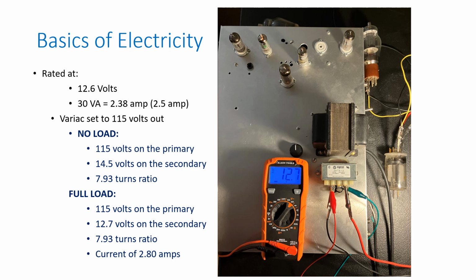So you might be asking yourself, well, now wait a minute. Why doesn't the voltage in my house vary when the air conditioner starts or the clothes dryer is running? Well, it does a little. It's going to drop a little. Here at the house, if I turn everything off in the house, I get 123.4 volts, about that. If I turn on the clothes dryer, the air conditioner, the oven, and the electric range and turn everything on, I can drop the voltage to about 117. Now, it's only a few percent less.